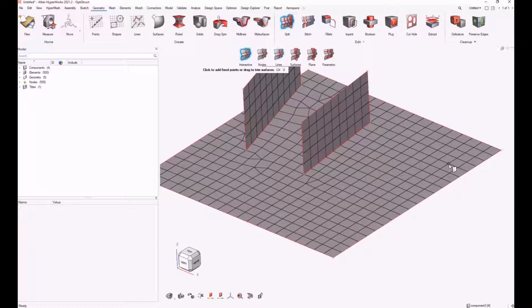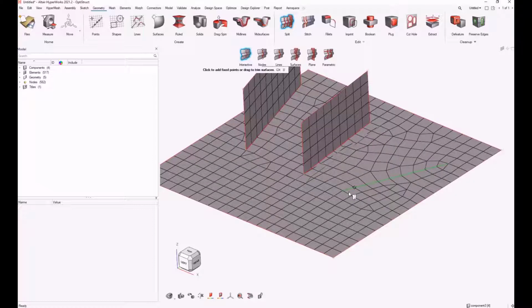Pick a node and hold the mouse button, and you can see that I'm dragging a line, and I can do it either perpendicular, to an endpoint. You can see it goes perpendicular. It snaps to nodes. It'll go to midpoints here on lines. You saw that pop up. So it has a lot of snap features. But now when I snap to this node, it splits the line directly.